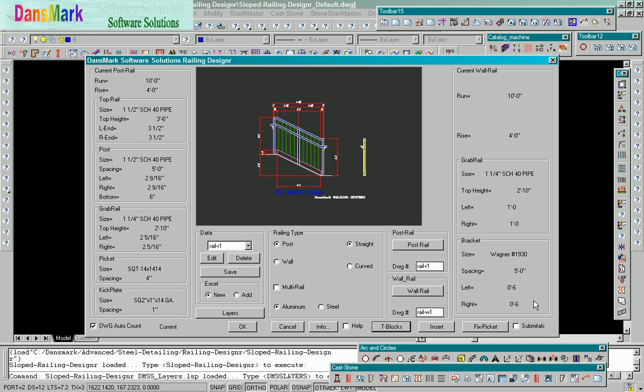railing system, and it's going to be on a set of stairs, and we're going to face mount the base plate so they'll be on the edge of the stringer or on the face of the concrete or however it is you're mounting. You have three options: core drill, base plate with plan view, or base plate with an elevation view so that you can mount these on the side. Depending on which one of those is configured depends on which submittal drawings are actually drawn. It will draw all the details that you need for a submittal.